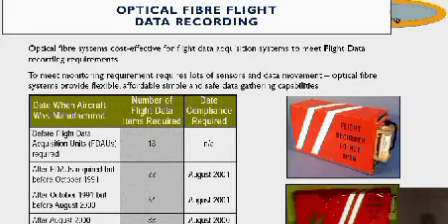The date when the aircraft was manufactured, number of flight data items required, date compliance required. Before the flight data acquisition units, FDIUs are required. Number of flight data items required, 18. Compliance not applicable. After FDIUs required, but before October 1991, the flight data items required were 22.